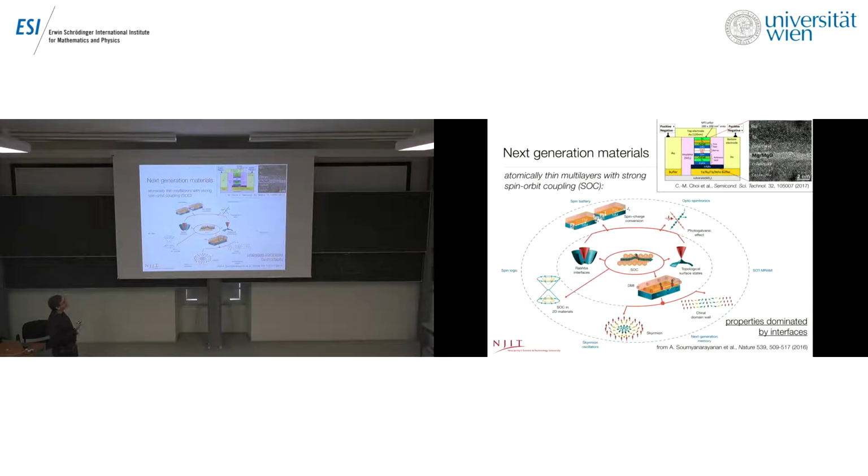And so this is a way to encode a bit of information in a single cell like this, and then by passing current through that arrangement, one could even read out the relative orientations of the reference and the free layer, or in fact affect the state of the free layer. And this would then correspond to the read and write operation in a magnetic memory cell.